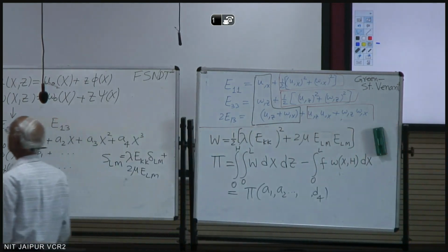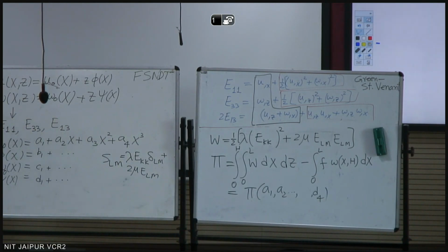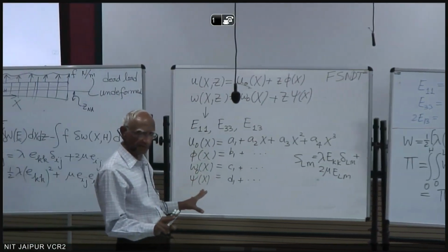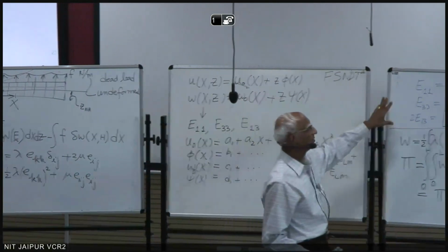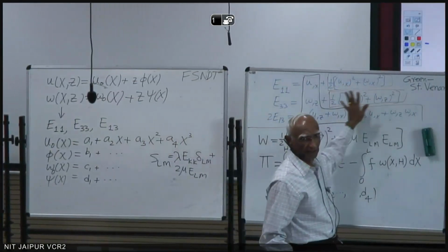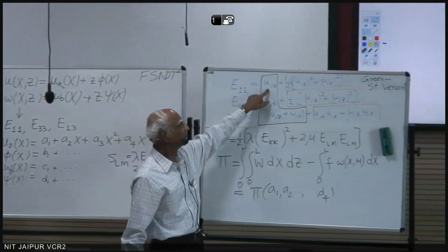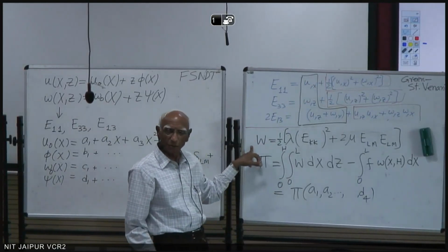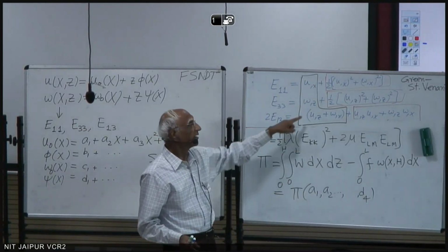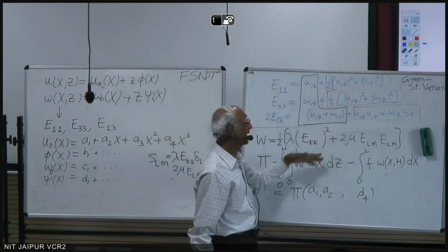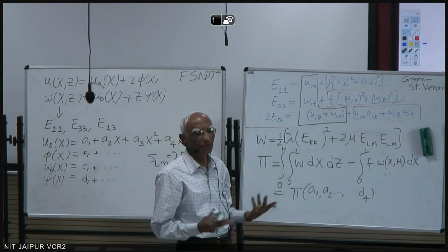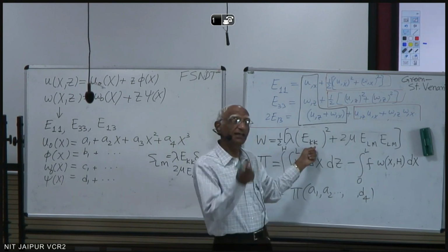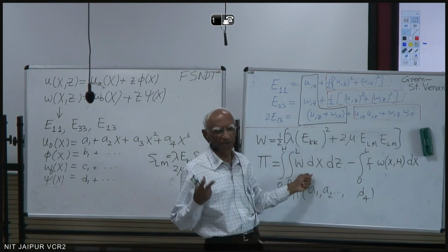Okay. So still it's a minimizing procedure. This is the same for both small and large deformations. For large deformations, you find E from all of these terms, keeping these ones and these ones. Then you find the stored energy density. Because these are quadratic terms, they will have A1 square in it, A2 square in it. And also, when you come here, you are going to square again. So they will have A1 to the power 4, A2 to the power 4, something.